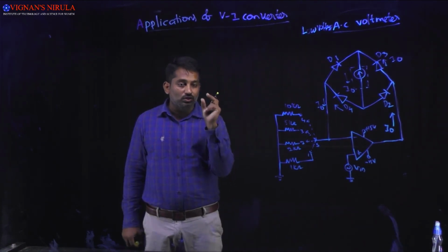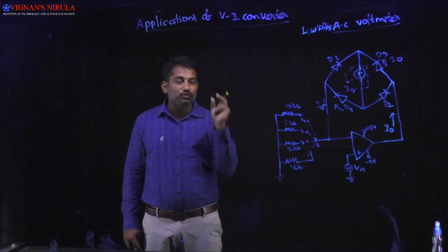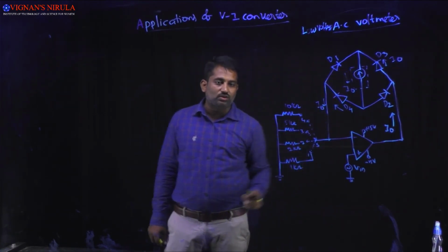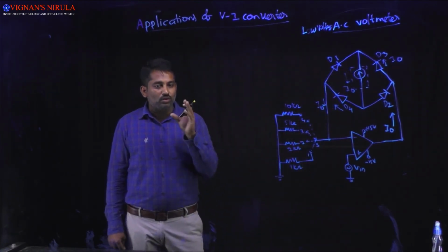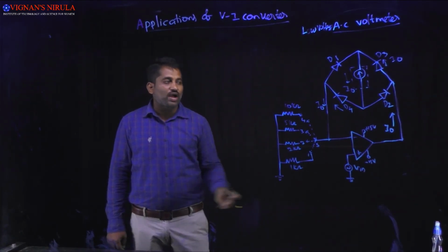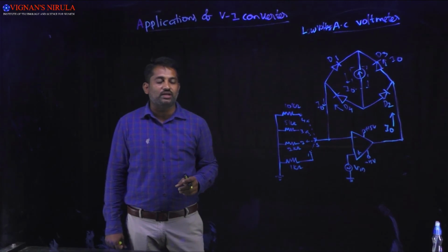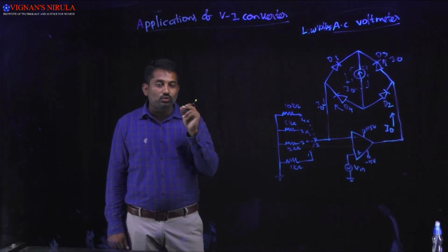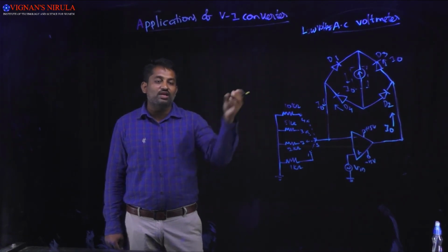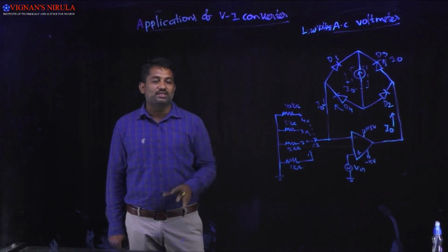And one more thing you have to remember is, if you want to calculate the RMS voltages by using the D'Arsonval meter, then you have to include a factor 1.1 for the calculation of RMS values for the input sinusoidal signals.